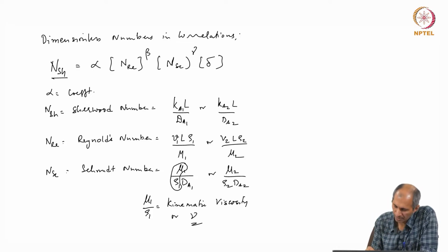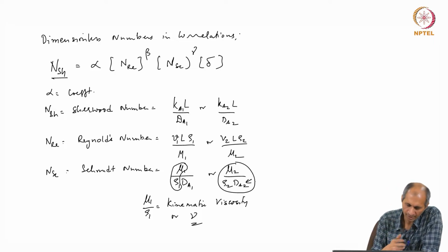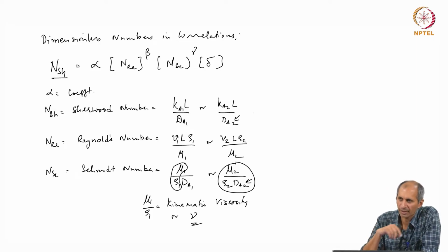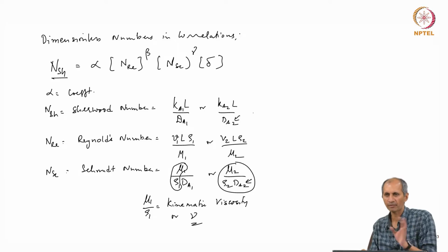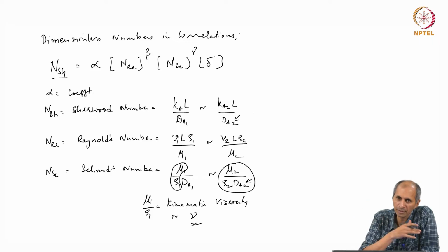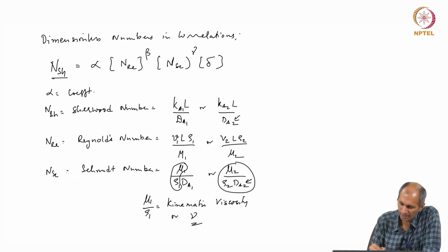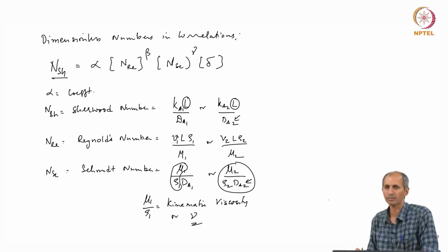So this gives you some idea. If this exists in the correlation, this has this factor dA2. So dA2 will account for the particular compound that is there, it is now scaled to that particular compound. There is also dA2 in the Sherwood number, so this will also add to that scaling. A good correlation takes into account all factors, which means somebody has taken the pains to do the experiment for a wide set of compounds, diffusion coefficients, and then for a wide set of velocities and geometry. But this is still geometry, meaning this L here is some length scale.